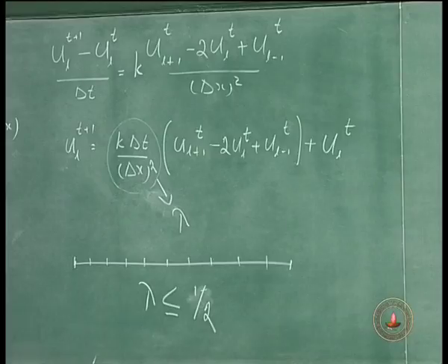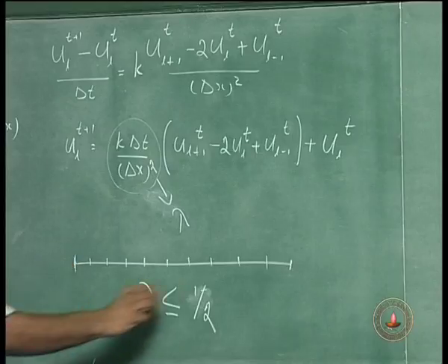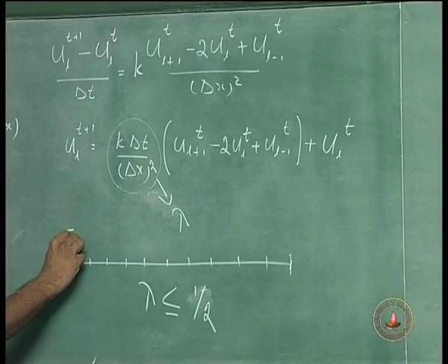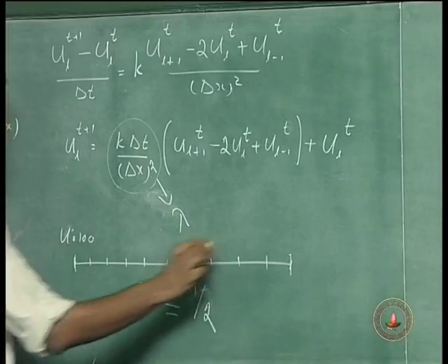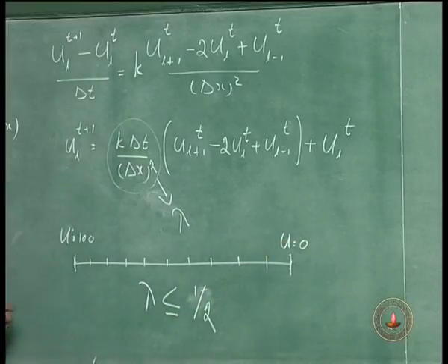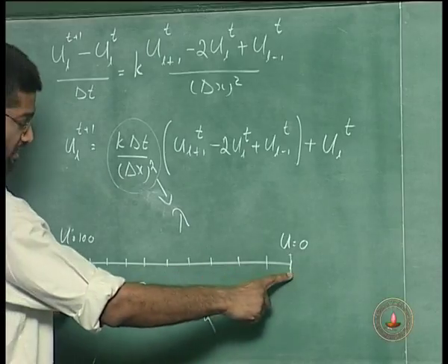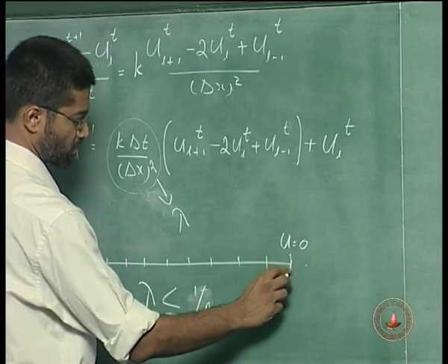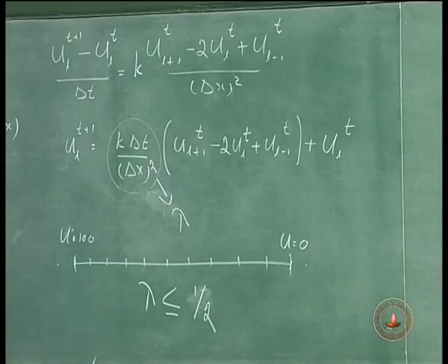Okay. So we have to use some boundary conditions. The boundary condition could be that at the two endpoints the temperature is specified. So we could say that u is 100 here and u is 0 here, or we could use the derivatives at the two boundaries. If you fix the derivatives at the two boundaries and get the temperature corresponding to two fictitious points on that side, so that the derivative can be fixed, then we would have to solve for all the points including the boundary points.